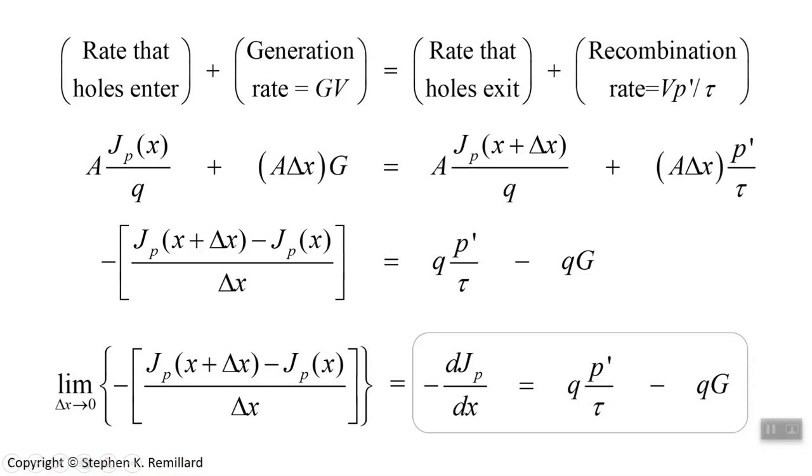Remember, there are two types of currents we've talked about, diffusion and drift. The expression for J for drift was just nEv, or pEv for holes. And for diffusion, it has the whole gradient in it, which could be convenient. Which one of those should we have? All you have to do is add them together, so this J could be the diffusion current plus the drift current. You can do that, and this will be a more complete expression.